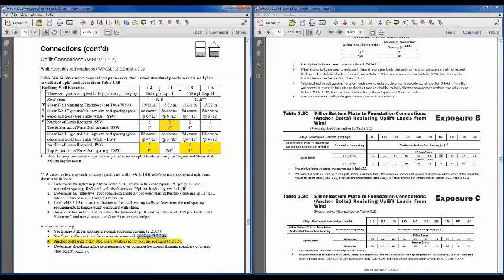The other note here that's highlighted at the bottom is that when you design these panels for combined uplift and shear, your anchor bolts need to have 3 by 3 inch steel plate washers at 16 inches on center, because with that additional uplift in that sill plate, you're putting cross grain bending stresses on that sill plate, and so what we found was that would split out around a normal size anchor bolt with a washer, and so that's why these 3 inch by 3 inch plate washers are required.